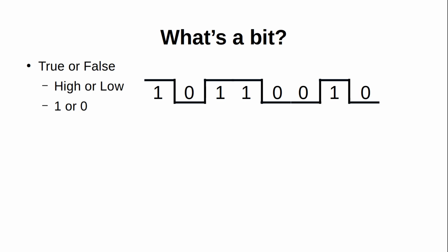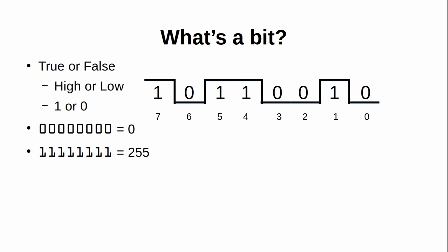To review, a bit is nothing more than a single binary state: true or false, high or low, 1 or 0. Bits are the basis of digital computing, as there is no in-between value, which makes things simple on a basic logical level. A byte is 8 bits, and in the mnemonics of Z80 assembly language, they are numbered 0 to 7, with 0 being the lowest bit at the rightmost position. Bit 7 is the highest bit at the far left end, which is also used as a sign for 8-bit values. With 8 bits, a byte can have 2 to the 8th power different values, which works out to 256, with a range of 0 to 255. But for the purposes of this lesson, we don't care about the numerical value of the byte, only the values of each bit. Now, let's see how we can deal with them individually.